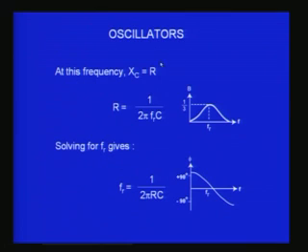What is important is when xc becomes r, that corresponds to the condition r is equal to 1 by 2 pi fr c, where fr is the critical frequency. You would find you get a maximum at that point, and the fraction, beta, will become 1 by 3. So the frequency is 1 by 2 pi RC.